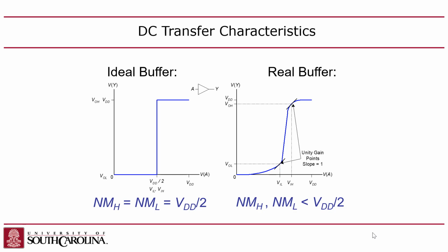And so the difference between VIL and VIH is fairly small. So there's a forbidden zone there that's fairly small because of the way the logic gates work: the forbidden zone for the output voltage is essentially much wider, because even if you give it an input voltage as high as VIL, the output for that is not that high a voltage compared to VIL.